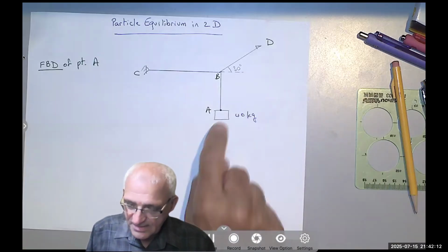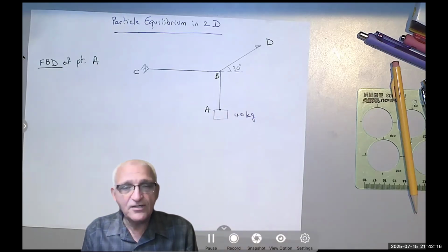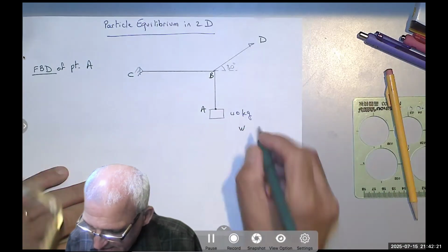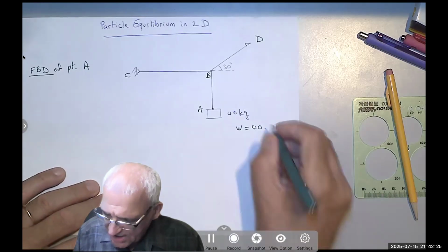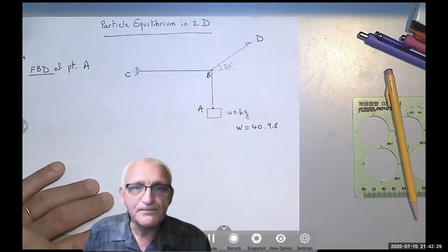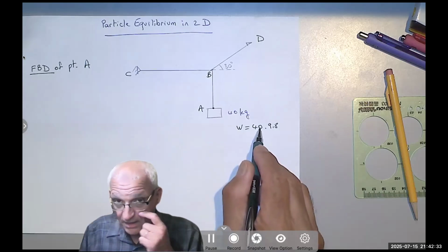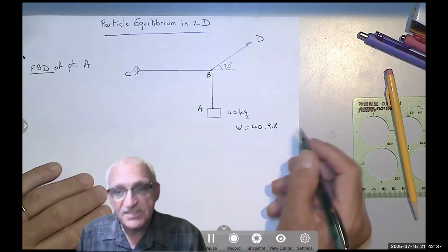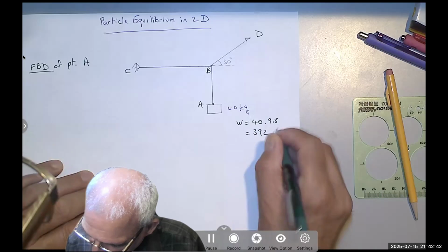First of all, this is a mass, not a force. A mass of 40 kilograms. So we are going to say the weight of this box equals the mass times the Earth's acceleration, and usually we use 9.8. Okay, that's good enough. So you see the decimal place you can cancel with the 0, and you just get 392 Newton.